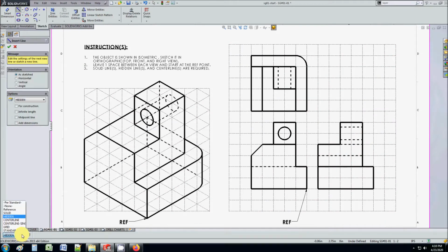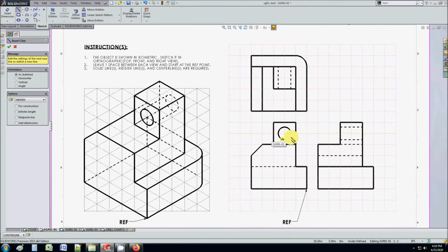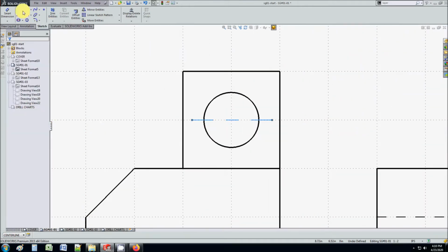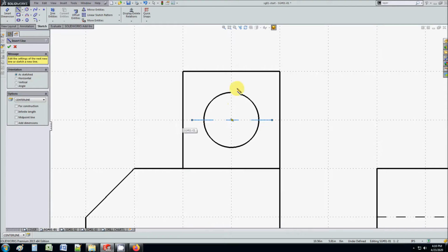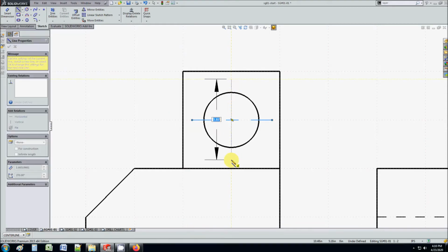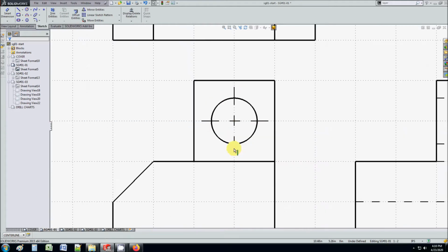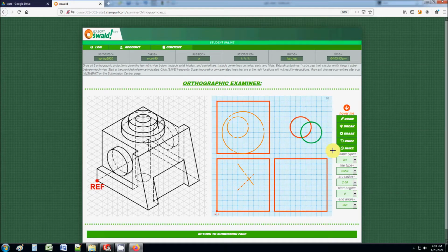Finally, I'm going to add my center lines. And we're just going to... on the exam, make sure it's one cube past, okay? I'm not doing that here because in a drawing, usually it should only be 1/8 out, something like this, but for the grading algorithm, okay, remember, if you have a circle, you are going to draw one cube, just like that.